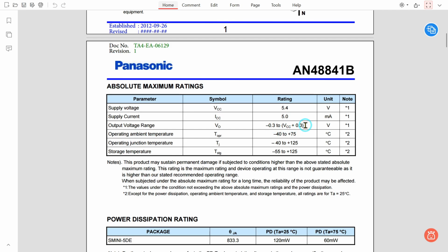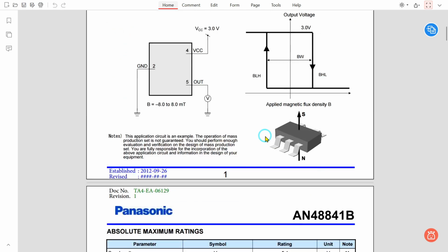In any case, these pins are connected. The output pins here are actually connected to the GPIO pin, so therefore we can do an analog read on them, and the maximum that it'll come back with is going to be 4095, which I've determined is true, and the minimum is going to be 0, but some of them are actually coming back with a very slight voltage. So it sometimes comes back with 0, 1, 2, or 3 or something like that, so we can take care of that in the code.